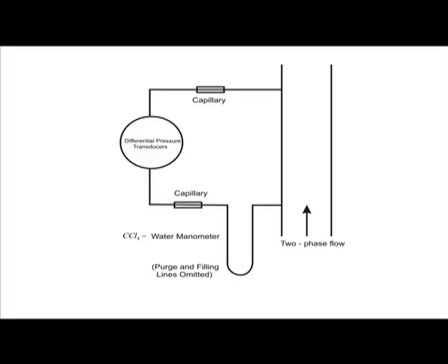Anyhow, so the thing is, so therefore, this offset, if it is compensated by some means, then in that case the differential pressure transducer, the DP transducer, it can be used to measure pressure differences, very low pressure differences, if the offset is compensated in some particular way. What can we do to compensate the offset? A very common technique is we use a compensating manometer.